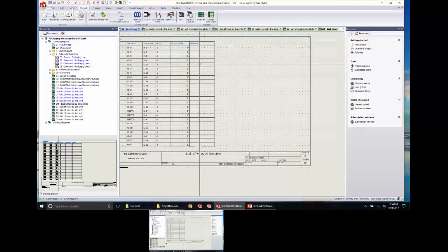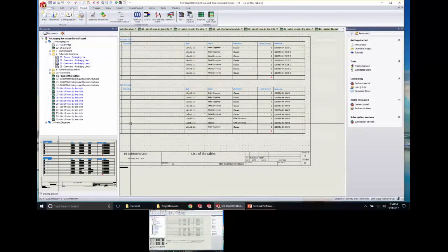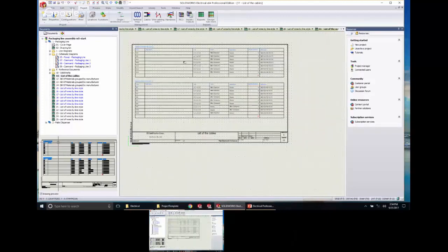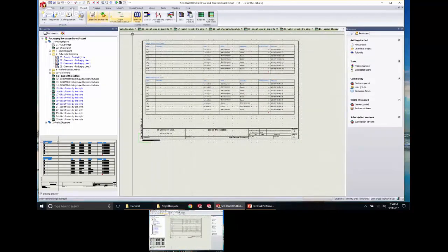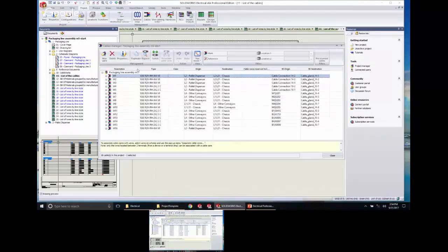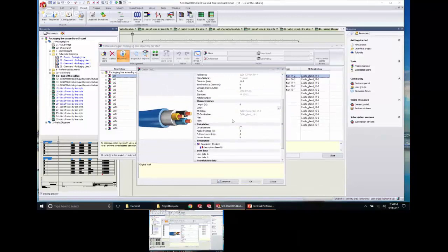Is there a different treatment for like the manufacturer part that is a 6-foot Ethernet cable or something like that, where it's got a defined length by itself? Great question. So Ed asked if you had a manufacturing cable, like off the shelf. You would define that. So see, there's a length here. You would make that part of that cable when you define the cable. So if we go back to the cables, for example, this W10, you go here and you assign it a length right there. And that's what you would do.